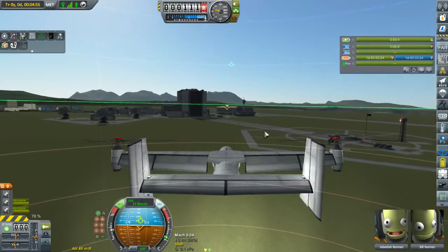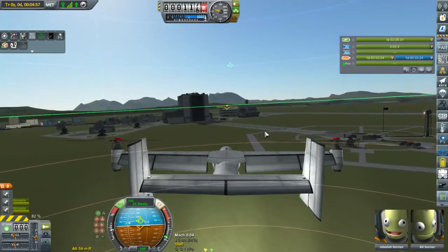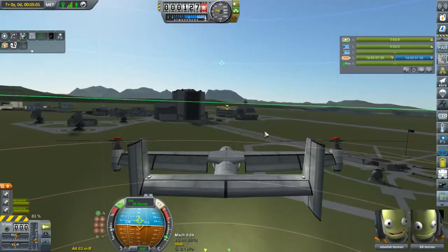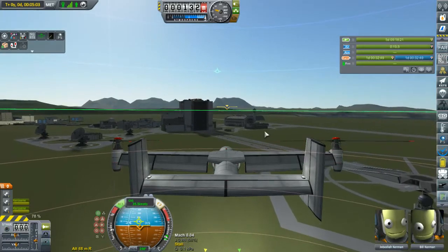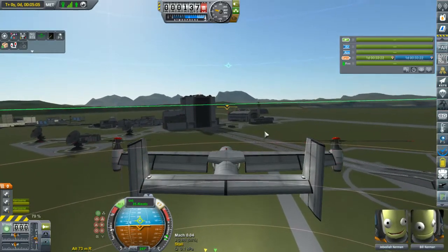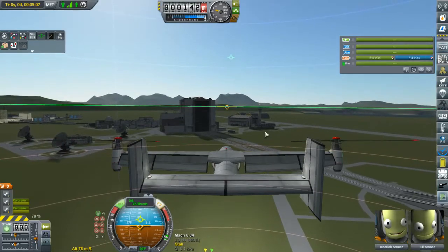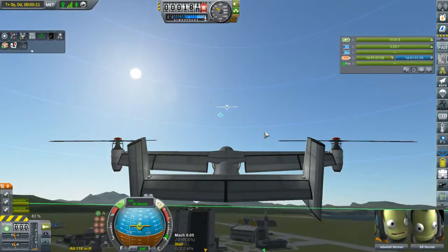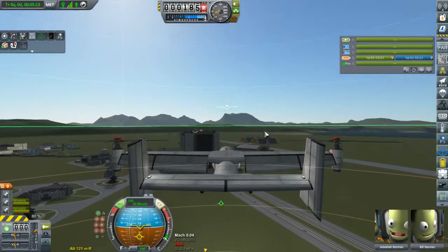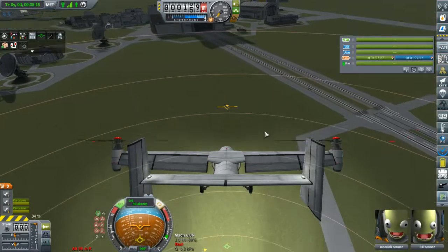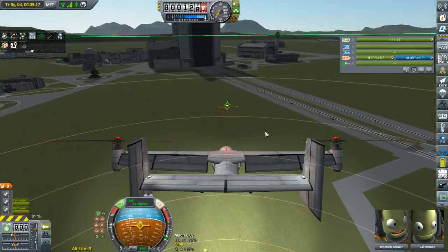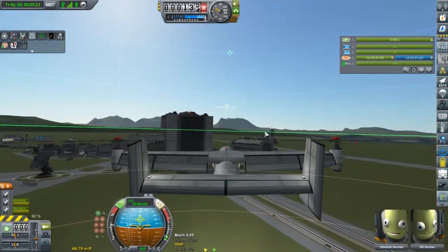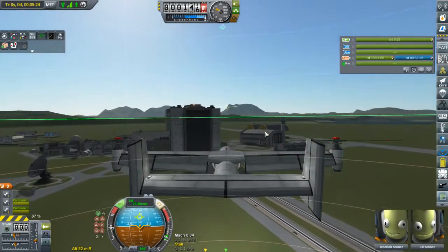Now, one of the behaviors you may see is you've got to remember that the huge tail plane on the back of the tilt rotor acts as a lever to your center mass fulcrum. So a high-speed climb in a helicopter-like configuration translates into a force down on the back of your aircraft. If I do this and add just all the collective in the world, I end up losing control after a certain point. Same is true in reverse. All the way back on the stick, no control. Luckily, thanks to the rapid response of the collective, I can come out of those. Although in real life that would probably stress the airframe something fierce, especially if it's loaded.